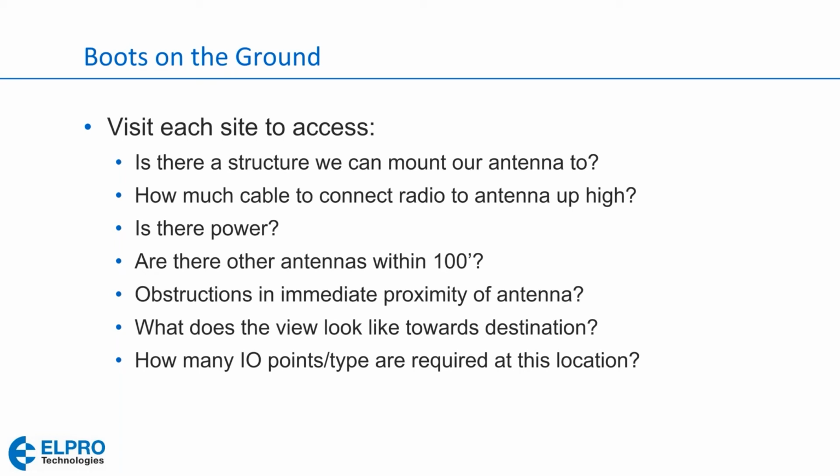And then, of course, to be able to pick the correct model of radio, we need to figure out how many I/O points and what type, like how many 4 to 20 signals and how many discretes, or is it Ethernet, or what's the interface at this location.